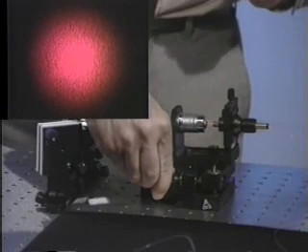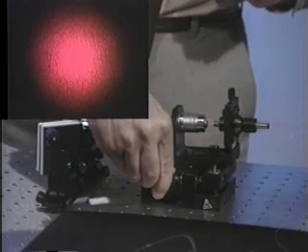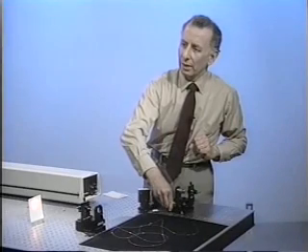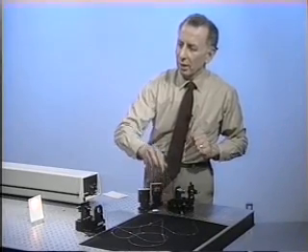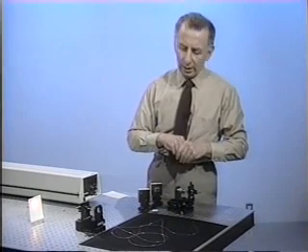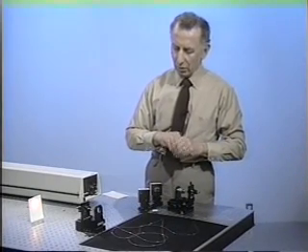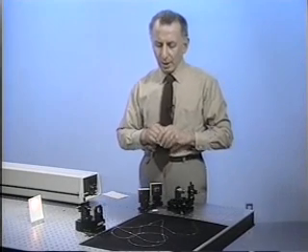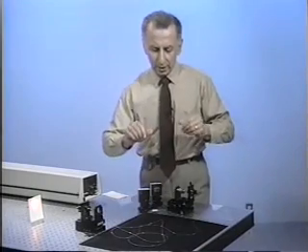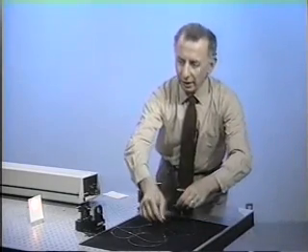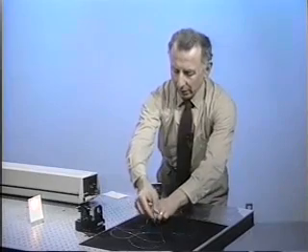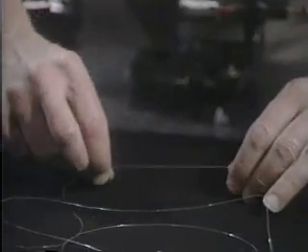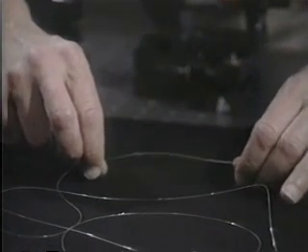So remember, the core is 4 microns, cladding is 125, the wavelength of the light is 6328 angstroms, and the core to cladding index difference is about 1 part in 10 to the 3. So this way you can show that indeed you get single mode propagation. Now I would like to illustrate some interesting phenomena about fibers. So if we get the camera to look over here, I want to illustrate how touchy is the propagation of light in a single mode fiber.